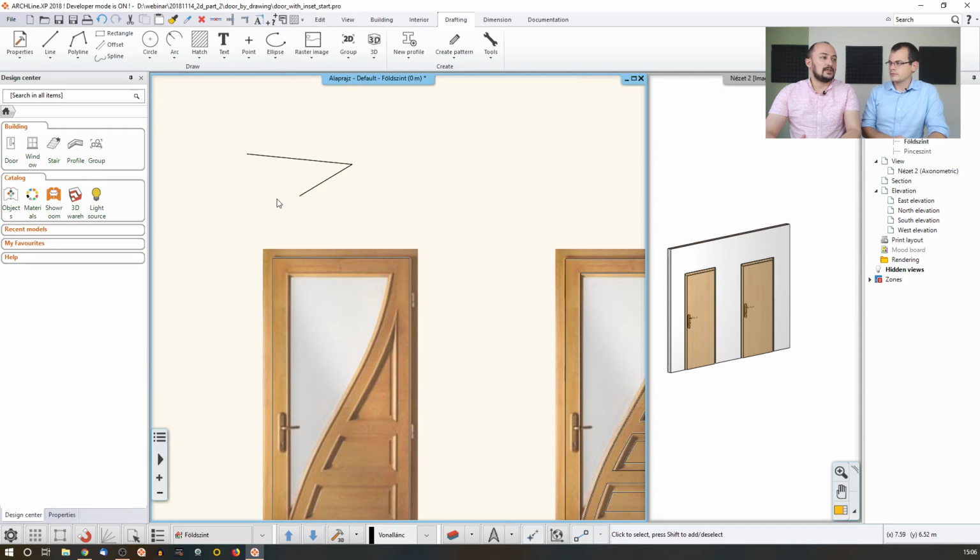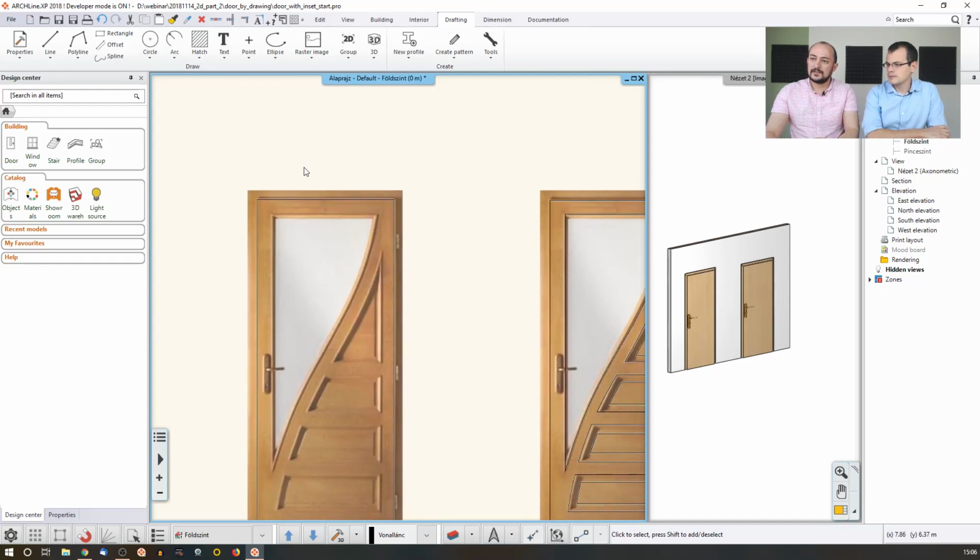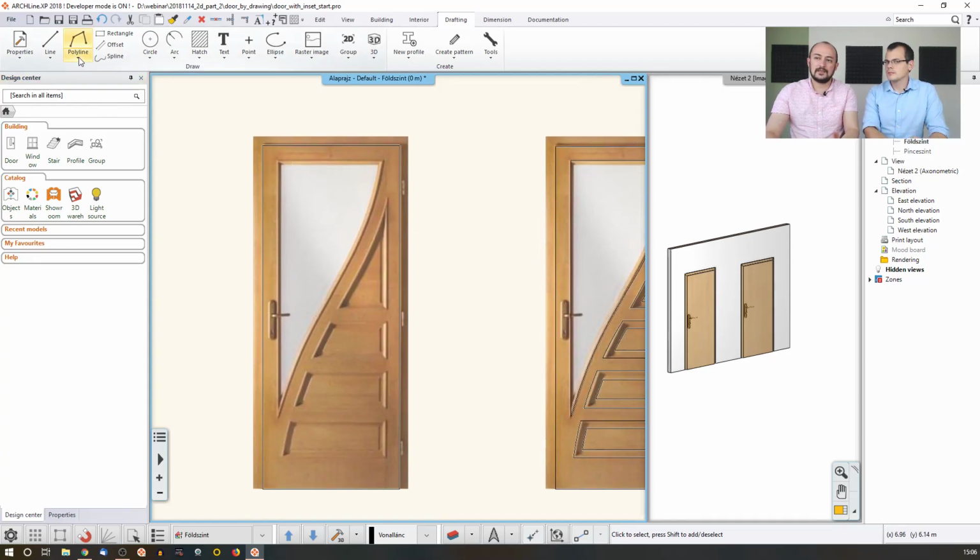You would like to create an open ending profile, an open half circle, half roof profile, or anything like that, you will use perhaps any of these. Or we covered this as well. If you would like to create a revolved item, this is also something that you can do. You just create a half profile of a glass or something like that, and you just revolve it around, and you will get the result. So now to create this, as you can see, there are many options.